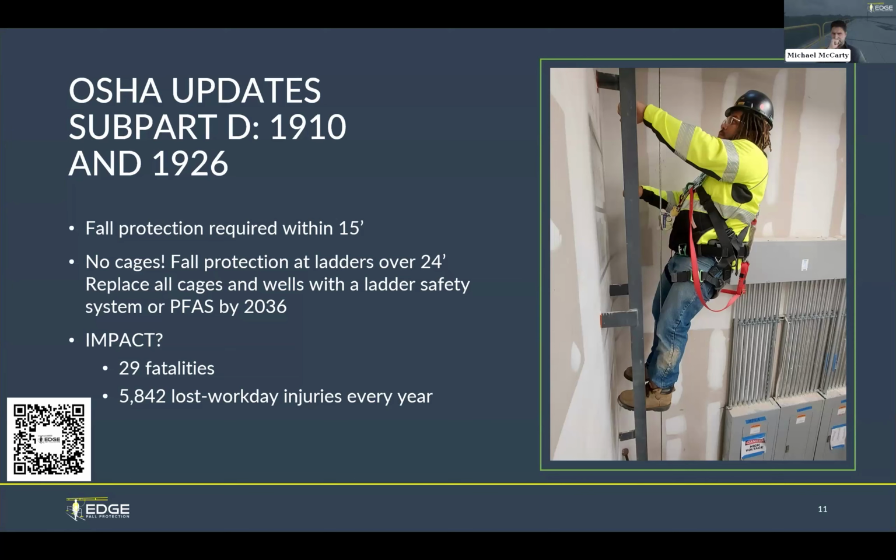We get the question a lot: Hey, what do I have to do with my existing cage? Do I have to replace my whole ladder? No, you don't have to replace your existing cage. But you can have some issues with the cage adding some sort of structural integrity, so it can change the loads and the stress of that ladder. So just make sure we're doing some sort of design criteria and analysis on what the ladder will look like without the cage.